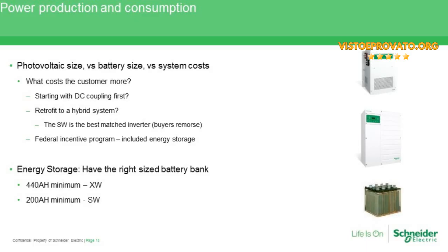But from panels to battery efficiency to inverter efficiency, they just start to add up along with wiring. So probably the most important thing to take from this particular slide is that understanding when the energy is going to be used is perhaps the most important part, and then also hearing what the customer is looking to use the system for.